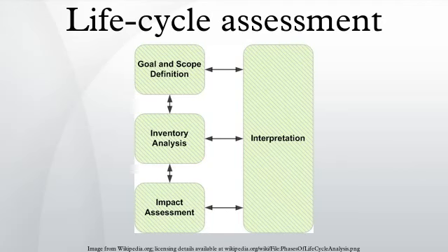Cradle to gate. Cradle to gate is an assessment of a partial product life cycle from resource extraction to the factory gate. The use phase and disposal phase of the product are omitted in this case. Cradle to gate assessments are sometimes the basis for environmental product declarations termed business-to-business EPDs. One of the significant uses of the cradle-to-gate approach compiles the life cycle inventory using cradle-to-gate. This allows the LCA to collect all of the impacts leading up to resources being purchased by the facility. They can then add the steps involved in their transport to plant and manufacture process to more easily produce their own cradle-to-gate values for their products.